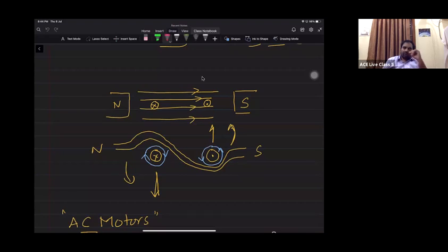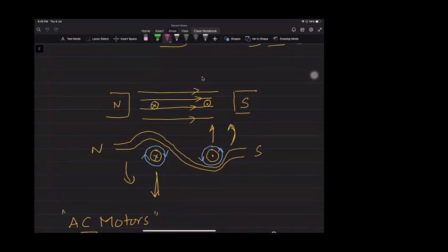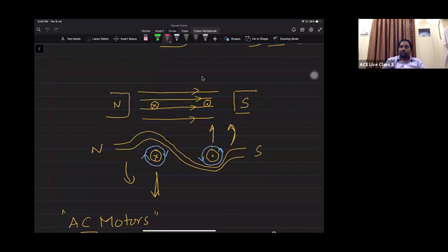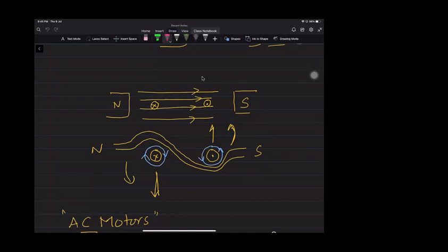When they are over excited, the amount of flux in the air gap will be more. Why? Because it is a separately excited motor. If the air gap is less and more flux is present, then cores will get saturated. So in a synchronous machine, the air gap length will be more. Basing on the type of the machine, we need to decide. It is not like in all cases it should be less. If a question asks in which motor it will be less, you can tell induction motor blindly. Understood? Yes, sir.